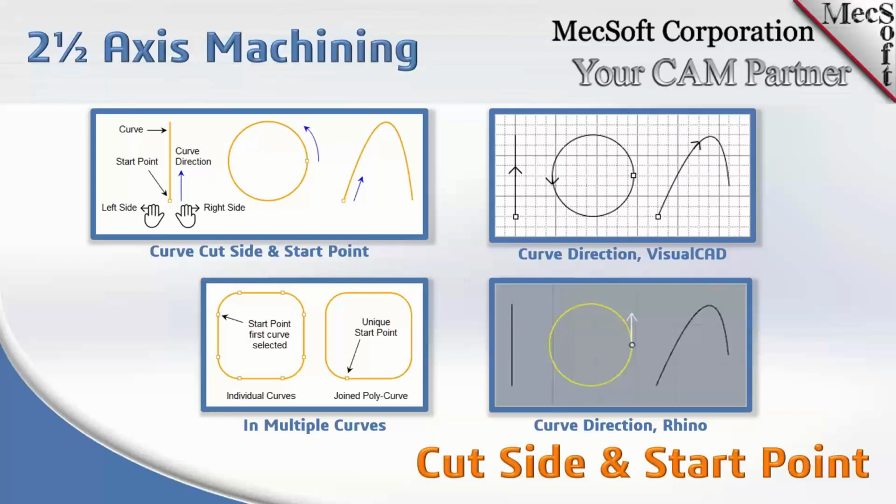That's also the case in closed curves. A circle has a start point and it has a direction. So if you want to machine the outside, that would be the right side of the circle in this case. If you machine on the inside, that would be the left side.